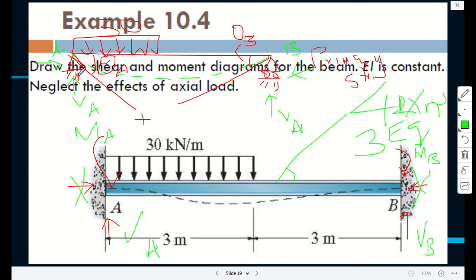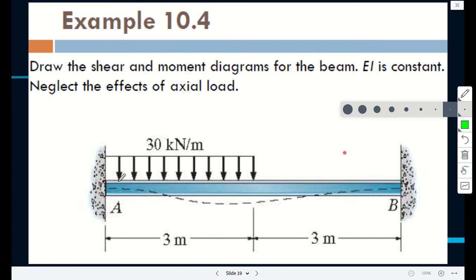To make it statically determinate, one has to be a roller and another one has to be a pin, for the one who has that question. That's the simplest answer. Actually, it's even much simpler than that, but that is the simplest answer I can tell you. When you make it statically determinate, you cannot put two pins, one at each end, because a pin means two reactions. Two pins give four reactions, which means you will not have solved the statical indeterminacy.